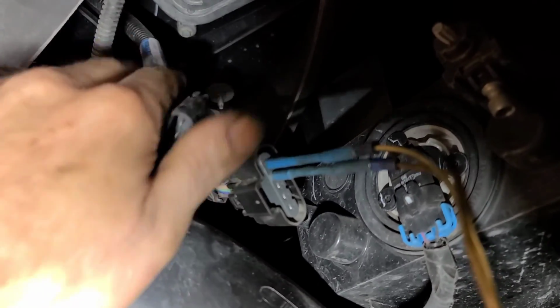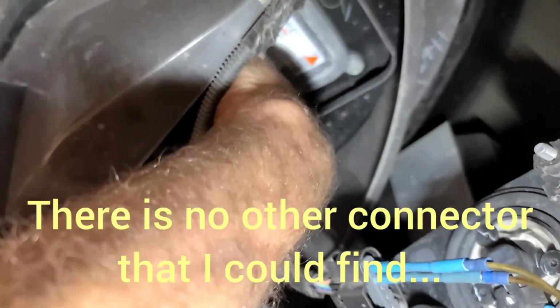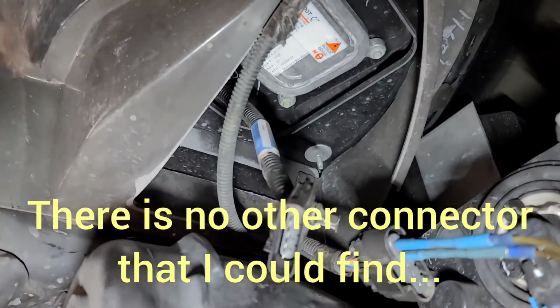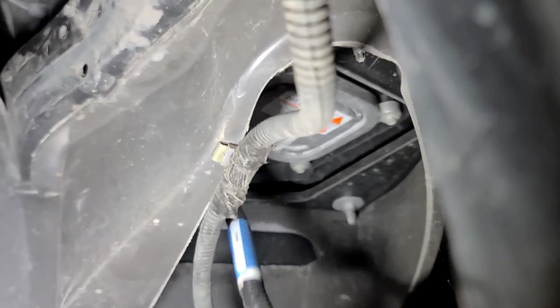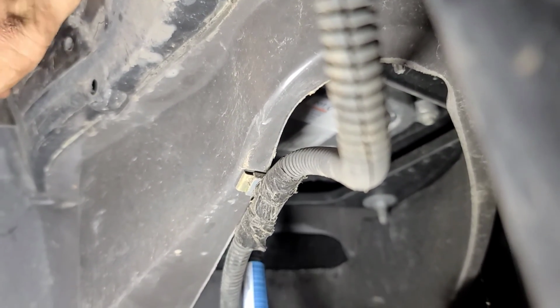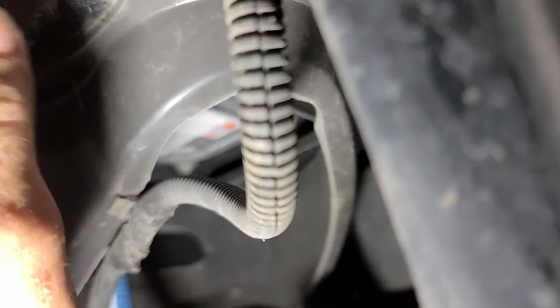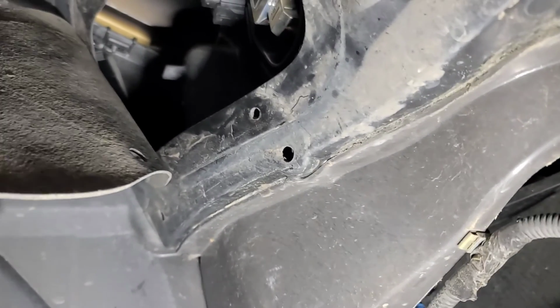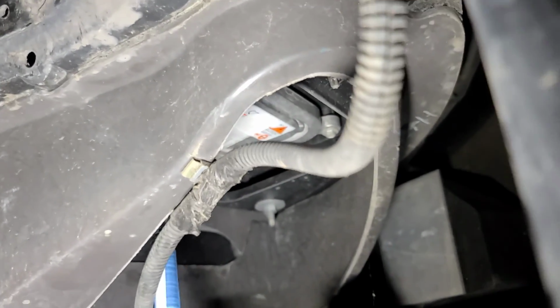There's supposed to be another connector up top here, and I don't find it behind this panel. So that harness goes right up behind the headlight, but it must go into some kind of a connector. I can't feel it. I can feel it up here. There it is there. It goes right behind this headlight, and this is all part of the inner fender. That doesn't look like 5 minutes to take out. So I'm wondering if we can take the headlight out.